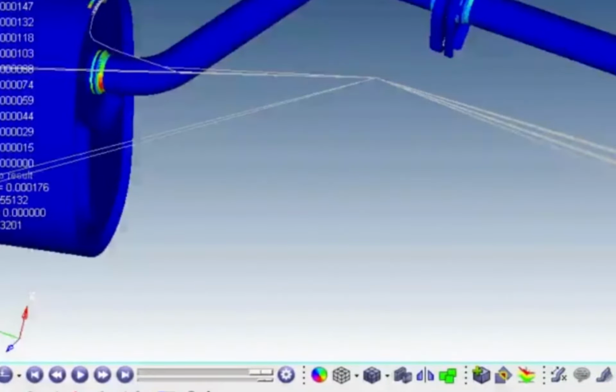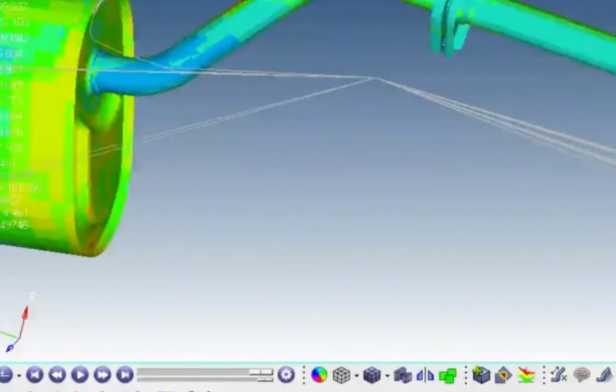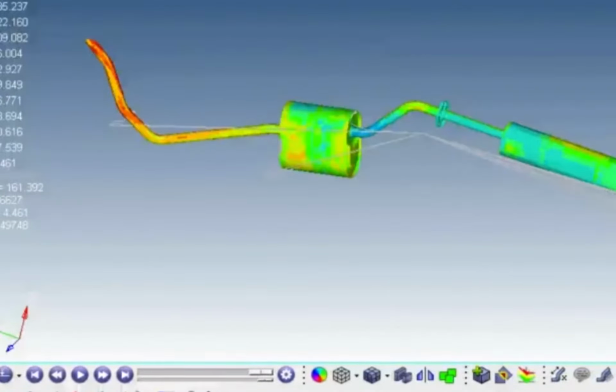Now I need to make my precision back to 3. If I plot zero crossings, it's the number of times this thing moves backwards and forwards in 1 second. This is loaded quite a high frequency, so it's roughly 160 per second. Let's see where that is. It's up here. But other parts of the model are responding less often, so their different modes are contributing to the response there. We can also plot the number of peaks per second, which is a more advanced statistic.